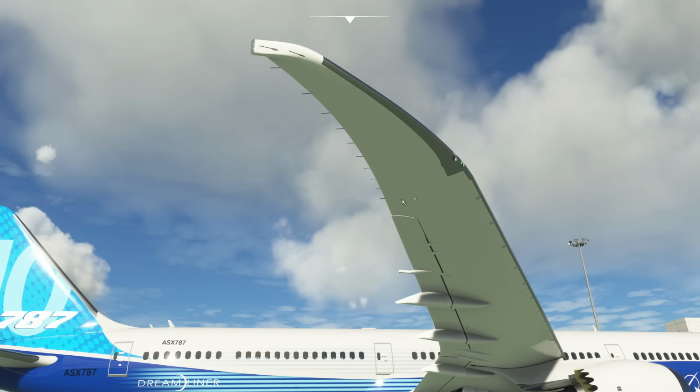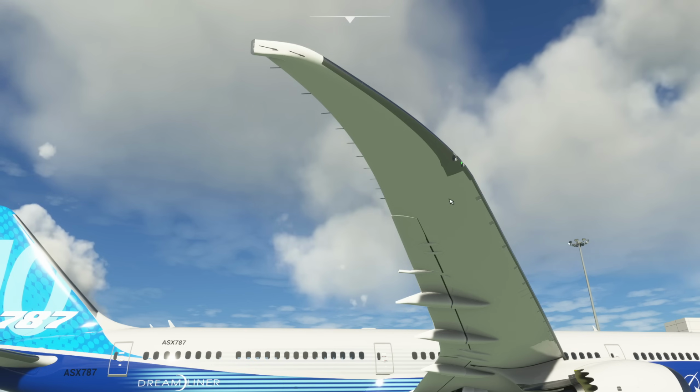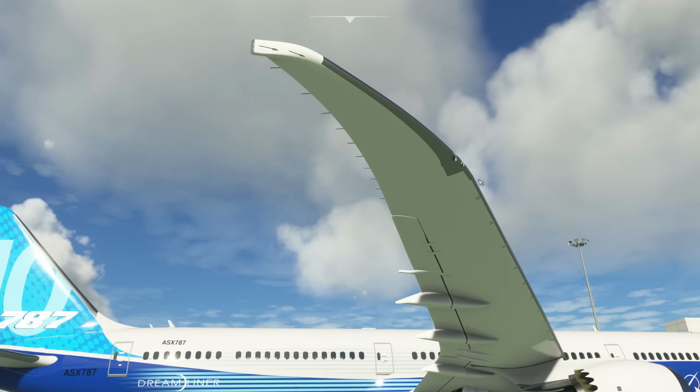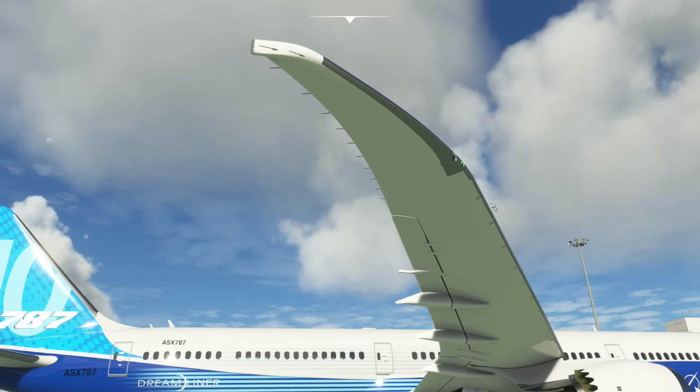Now, Boeing go with this for these long-range aircraft. It makes sense, whereas we can see with their short-range aircraft, the 737 MAX, they have a more vertical style of winglet, like you have on the A320 Sharklet and the A320neo. But for long-range airplanes like this, they have gone for this flatter sort of wing. As I say, the downside is it gets in the way.